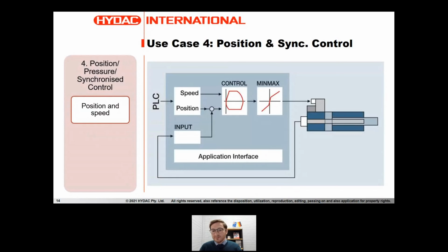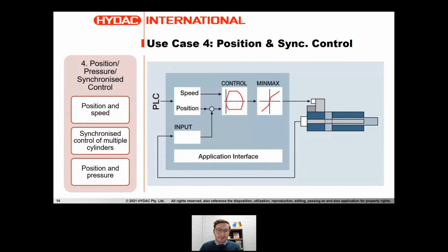For example, in timber mills, you need to drive saws to particular positions repeatedly, and then move it to another position. Really good option to let the device perform its own PID control, and it'll control it really precisely. Or you have synchronized moving.